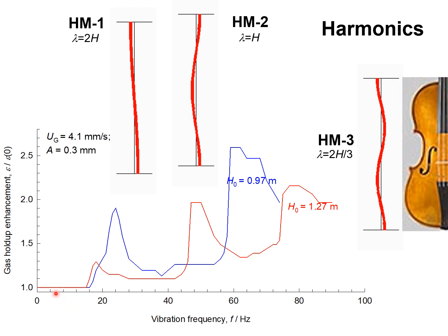And we note that the gas holdup enhancement is highest at a frequency of 24 Hertz, and then it reduces and further shows another maximum at a frequency of about 64 Hertz. And then it decreases.